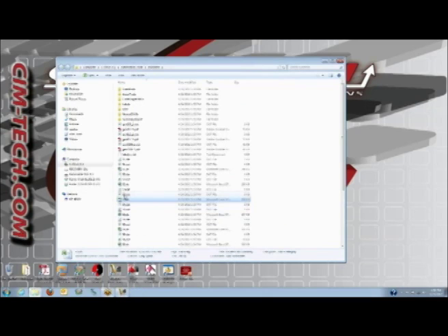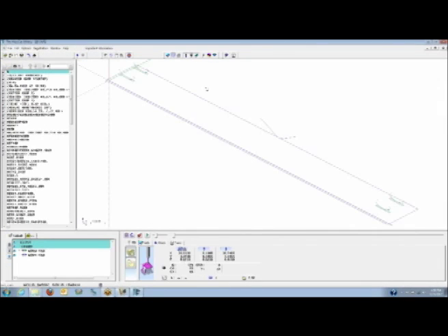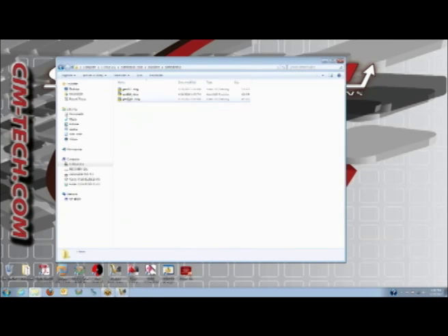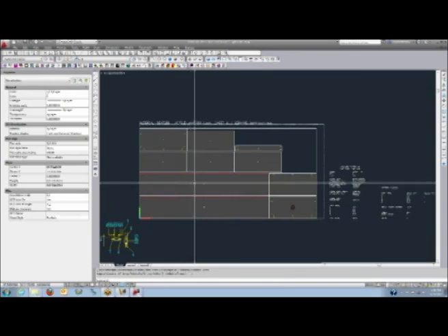We also have the single part programs available. So you've got the G-code file for the single part in there, as well as the G-code file for the nested sheets. The nested sheets are saved as drawing files that you can open up, and from the drawing file you can see the 3D solids are still in there. You can see the shaded representation of the solids. They came right from Inventor, and the parts are feature recognized and all the toolpaths are generated.